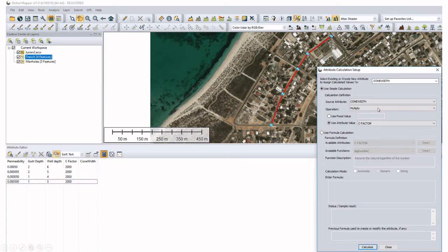Following on from that, I can use the attribute calculator to calculate those other settlement contours. First of all, I'm going to generate the width, so that's the radius for each of those variables, and next I'm going to then derive the millimeters of settlement at each of those 4 or 5 points.